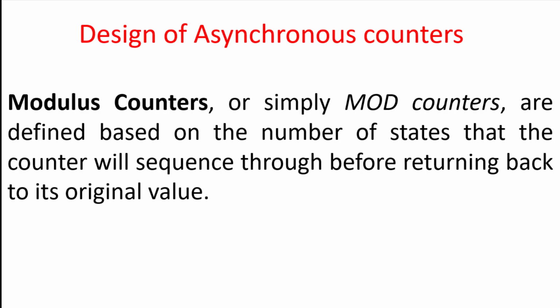So till now we have discussed how to construct up counter, down counter and up down counter. Now we are going to see how to design asynchronous counters, or simply I can say modulus counters. Modulus counters are special counters where we can define the counter outputs, like till how many states counter should count. Suppose if you take a 4-bit counter, which is going to take 0 0 to F, that means 16 states. Instead of 16 states I can restrict my counter to only 10 states.